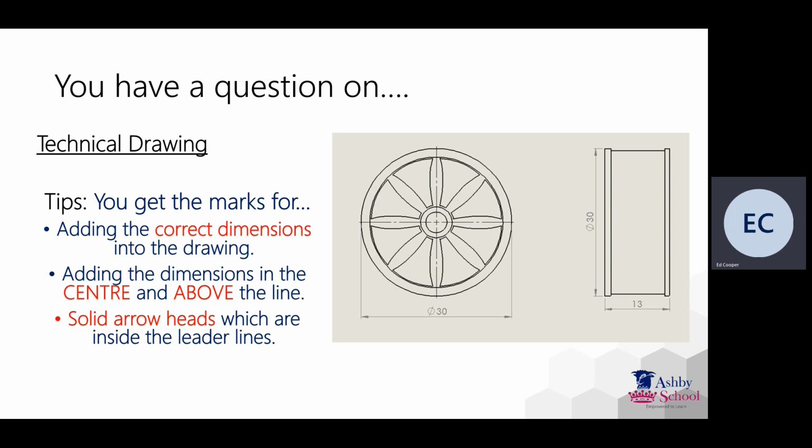So long and thin coloured in, number in the centre above the line, just off it. Arrowheads long and thin coloured in, remember that one. And that will give you your marks on the technical drawing. Okay, really straightforward.